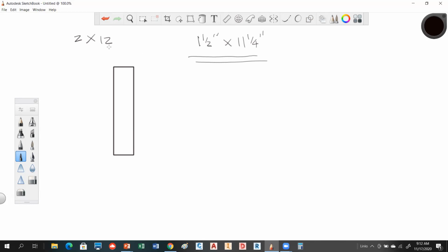The other thing about this chart, which is really cool, if you read over from the dressed size, you will also notice it calculates the area of the section for you. It gives you the section modulus. And remember, the section modulus is I over C. So you don't have to calculate that kind of stuff. And it does give you the moment of inertia.